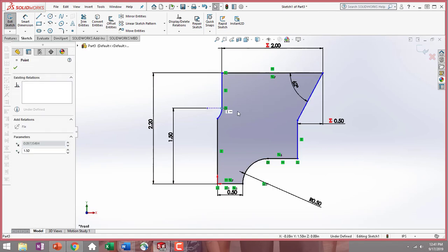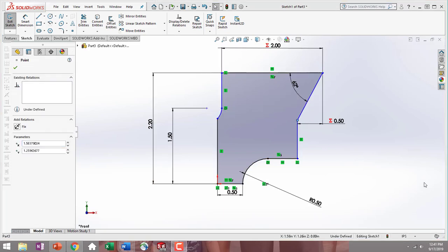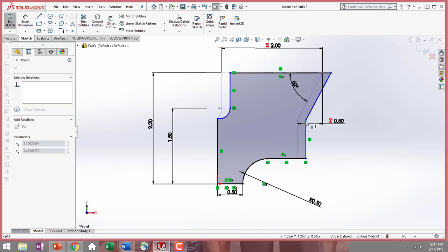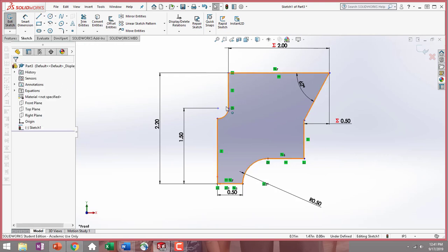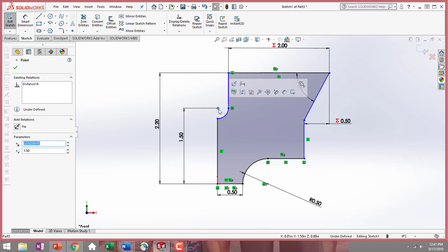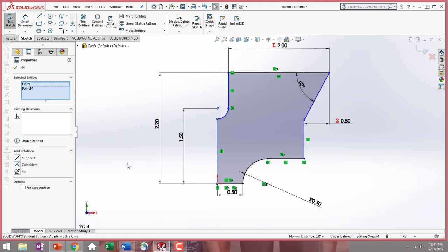Try to move your part around. Sometimes SolidWorks won't just snap things into place. So I'm just going to grab this outside edge. You can see I can move it, and as I move it, that arc, or that midpoint of my arc, moves as well. So now let's try to add in that relationship. So select your midpoint, hold down Control, select your line segment, and it's still not wanting to come up.